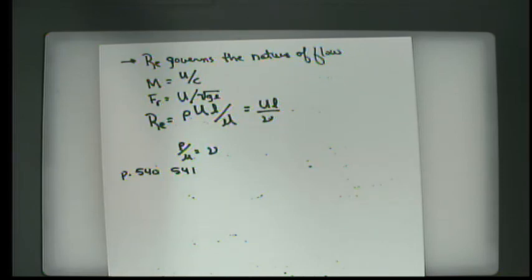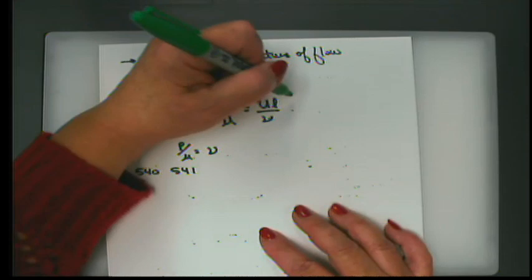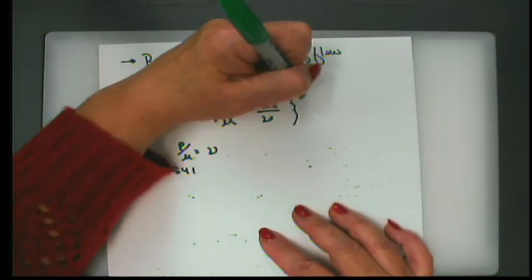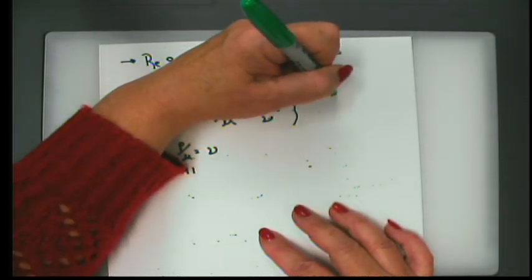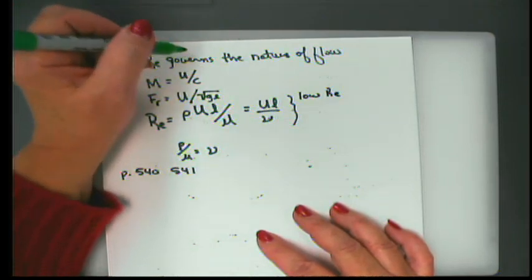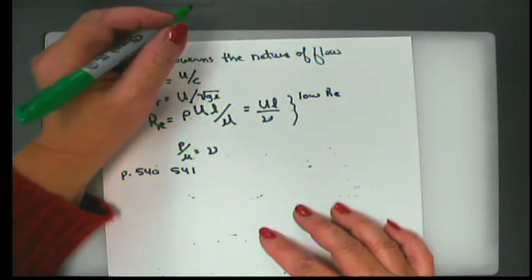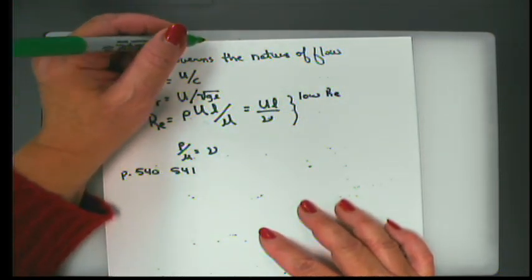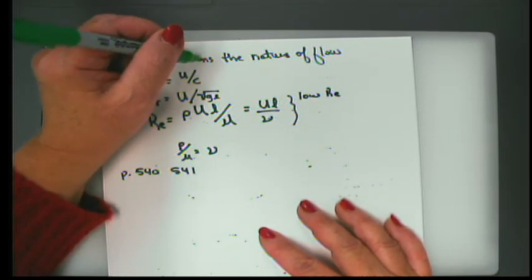And it says basically the gist of this whole idea is that the characteristic of flow past an object is dependent upon the value of the Reynolds number. And as usual, it's hard to quantify exact numbers, but we talk about low Reynolds numbers, which would be very, very laminar flow. And what happens there is that viscosity of the fluid is very important.